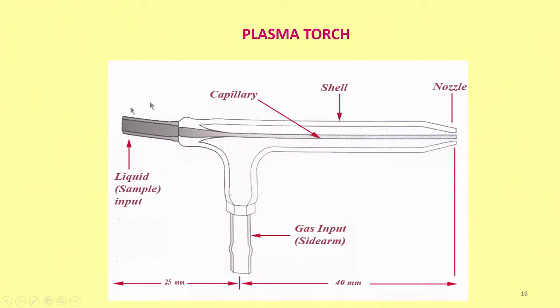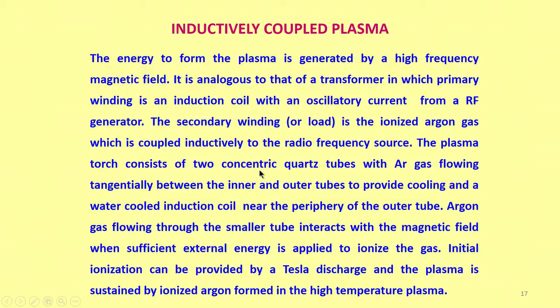I had shown you the figure just now. If you do not remember, this is the one, this is the capillary. So, the argon that is passing through provides a cooling atmosphere, it provides a plasma in front of this nozzle about 1 centimeter length. Here you can see I am pointing out 1 centimeter size, and that also generates high temperature.